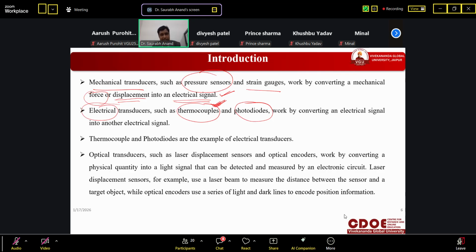If temperature is maintained, then it will switch off the compressor. Once the temperature increases at certain level, okay, so who will sense it? This transducer, and accordingly that will start the compression. Okay, so depending upon the transducer, it will work. It will start or stop the working of the compressor.